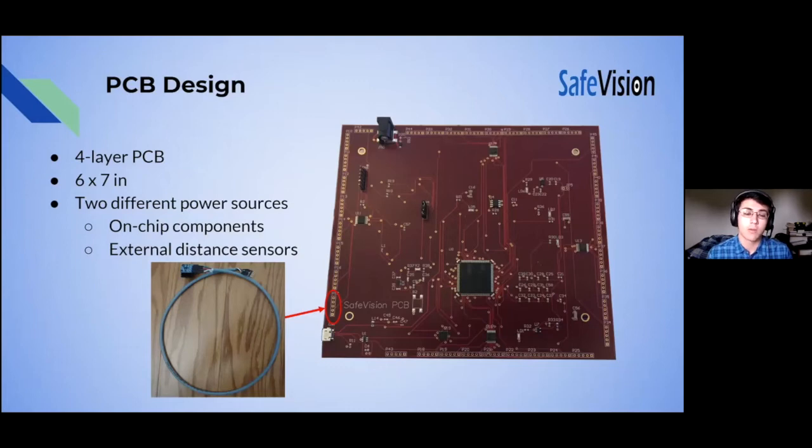This is responsible for powering all the sensors at the edge of the board, since the USB connection was not enough to supply power for the entire board and the sensors. Furthermore, although we're only using about 30 sensors, there's room for 36 sensors on the PCB in case we needed extra room for sensor expansion.